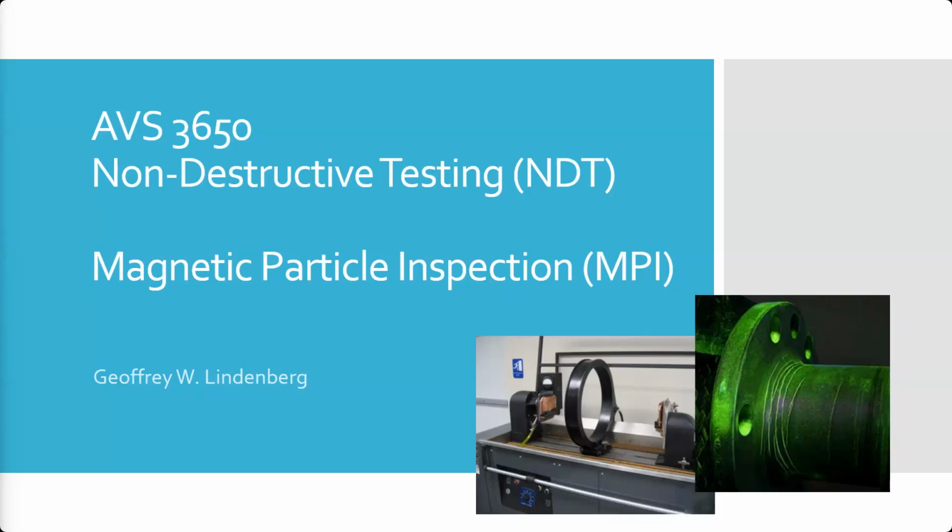Looking for those. Non-relevant indications would be things like, you have a certain amount of the particles on this flange, right? The outside of the prop flange usually isn't machined, it's the raw casting, so it's a rough surface. You can see some of the magnetic particles sticking to that area. Even though it's not a relevant indication, it is a non-relevant indication. Same thing with the holes right here, the prop bolt holes. Those are going to be non-relevant because that's just where fluid is going to pool. You can't do much about that. It's part of the geometry of the part.